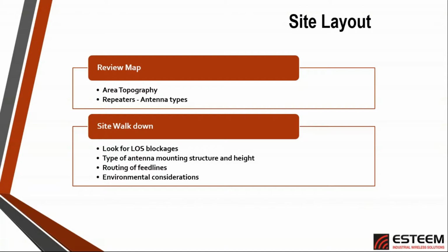The next thing we need to consider is what we'll call environmental considerations. Placing antennas outside of a smokestack, or putting them by the ocean where they're going to get salt spray, the antennas need to be protected from that. It's not that these are necessarily an issue. We just need to consider those and make note of them: where the equipment is actually going to finally be installed, do we have a plan for how to get that solved?